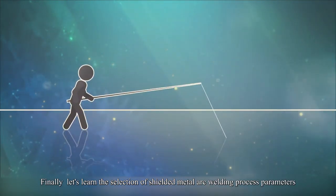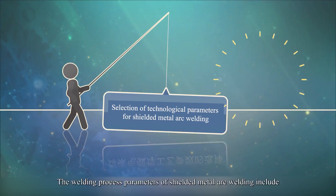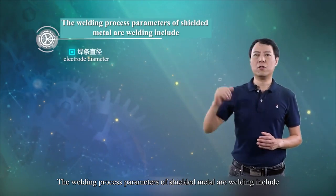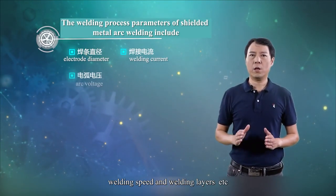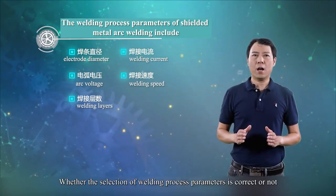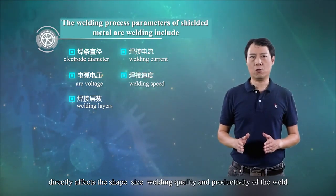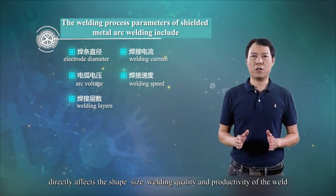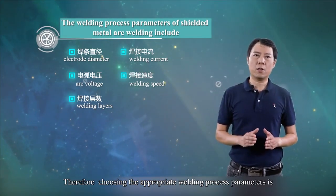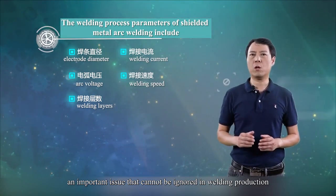Finally, let's learn the selection of shielded metal arc welding process parameters. The parameters include electrode diameter, welding current, arc voltage, welding speed, and welding layers, etc. Whether the selection of welding process parameters is appropriate or not directly affects the shape, size, welding quality, and productivity. Therefore, choosing the appropriate welding process parameters is an important task that cannot be ignored in welding production.